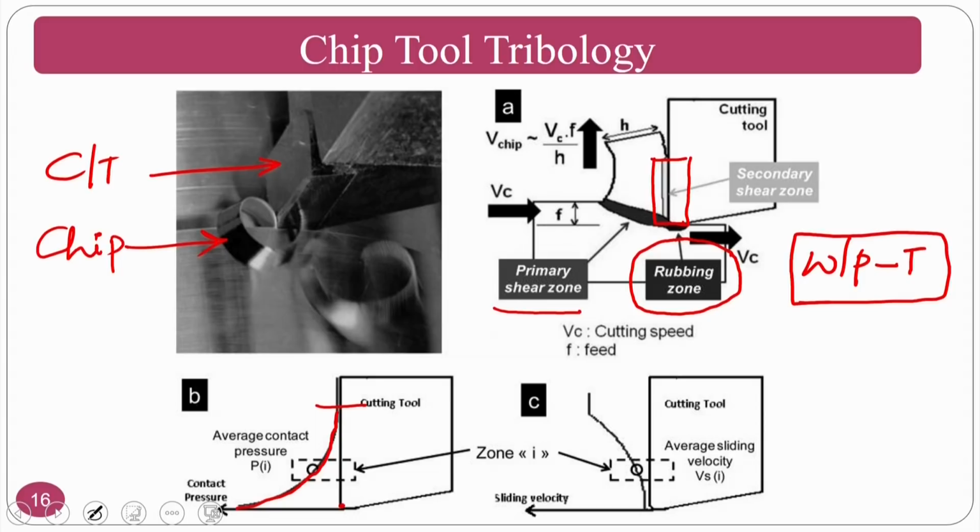You can try this, and in advanced materials, PhD students who are watching my slides can take up multi jets. Assume that I want to machine titanium with CBN or coated carbides, so you can use similar technologies. You can even use other technologies like cryogenic on one side and mineral oil based fluid on the other side, and all those things.